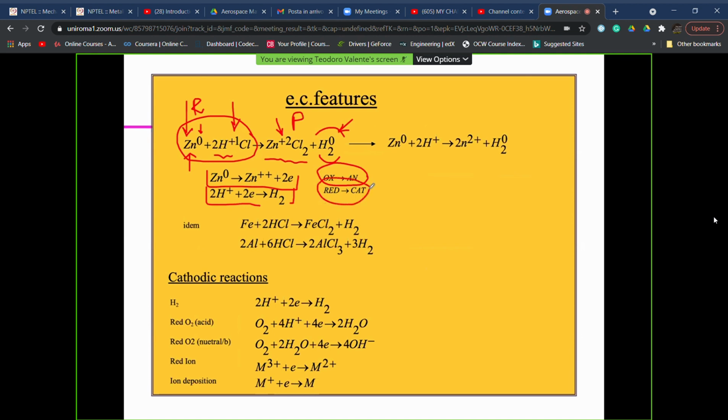In this case, at the cathode, generally speaking, we have the electrons left by the formation of the zinc ions consumed. Then, to come back to the general equation, these zinc ions, which go into solution due to the dissolution, that is the corrosion of zinc, can react with chloride -1 ions and then form, you see here, the zinc chloride salt, which is a product of the reaction.